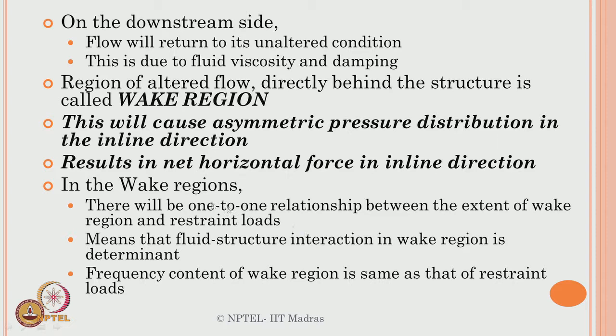In the wake regions, there will be a one-to-one relationship between the extent of the wake region and the restrained loads, which means that fluid structure interaction in the wake region is becoming determinant. You can calculate this in a closed form solution. The frequency content of the wake region is the same as that of the restrained loads.